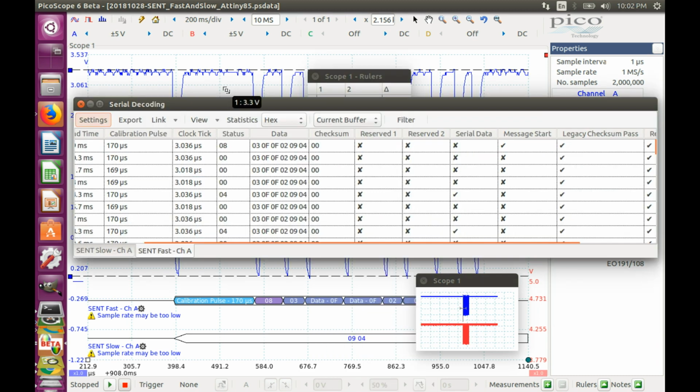It is easy to interpret the fast data. 3FF is the maximum value that fits in a 10-bit number. This MCU has a 10-bit ADC, so this is the ADC input connected to the power supply, and that's exactly what we did with channel A1. 294 is a value that is about 2/3 of the maximum that fits into 10 bits.